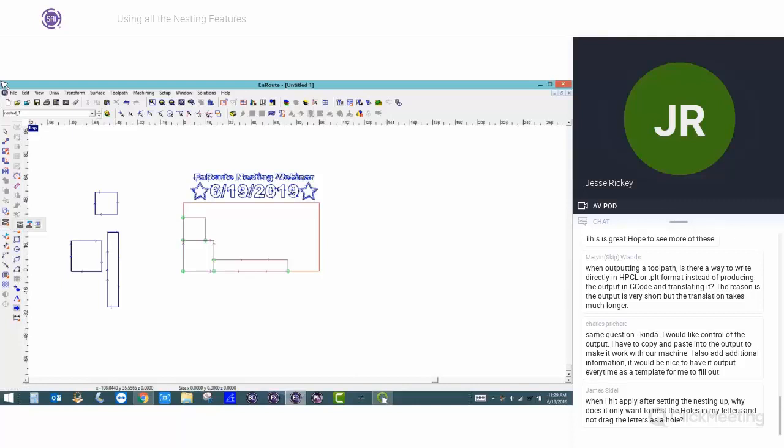Okay. So if we click and hold on that red triangle, just remember you have your nesting here, which you can either do true shape or block nesting. You have dynamic nesting, which is dragging from the top and moving in. You can scroll your mouse wheel in order to rotate that. And then you also have your nesting summary over here, which would create a printout of your different parts and your sheets as well.